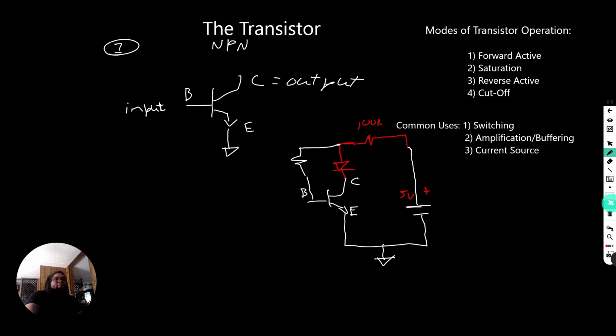When we don't have any bias voltage, like if this wasn't here, if we take that resistor back out and our base isn't biased, then the thing doesn't conduct, and that means that whatever is on this side, or the other side for that matter, doesn't see anything else. It can't complete the circuit.